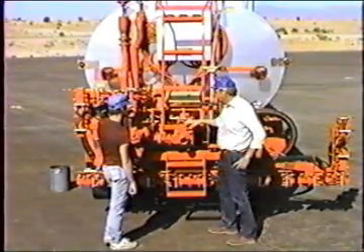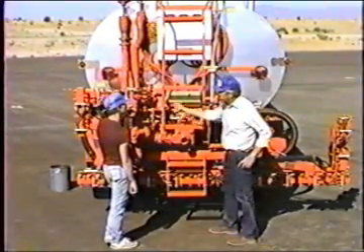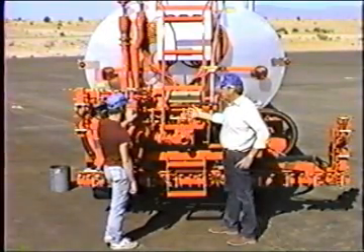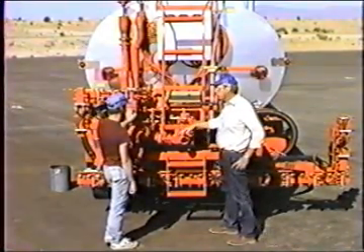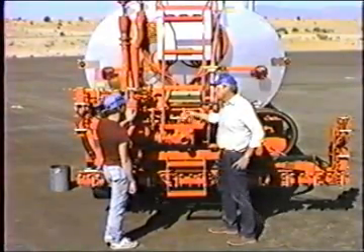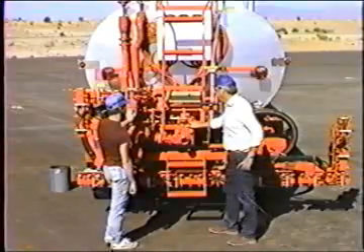The time to clean it is after the shift. It's when you're all done for the day and you have flushed the machine out. Then you've got everything shut off, and now is the time to take the screens apart and clean them, because you've just flushed with diesel. Everything is still warm, it's easy to get apart, and you can clean it out easily.